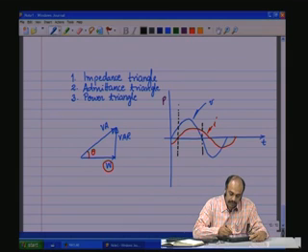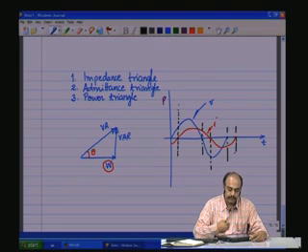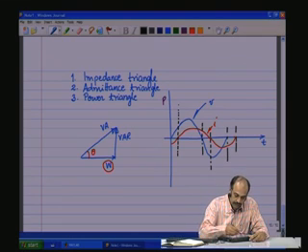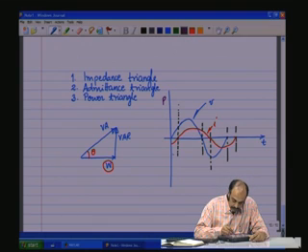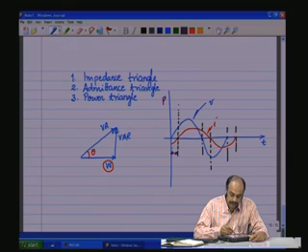This is another point of demarcation. There is one more important point of demarcation here within a period. Of course, so on it goes on. Here, if you look at the power during this period, what I have marked here, the current is negative, the voltage is positive. So when you multiply, the power is going to show negative. And during this portion, voltage and current are positive, and therefore it is going to be positive.